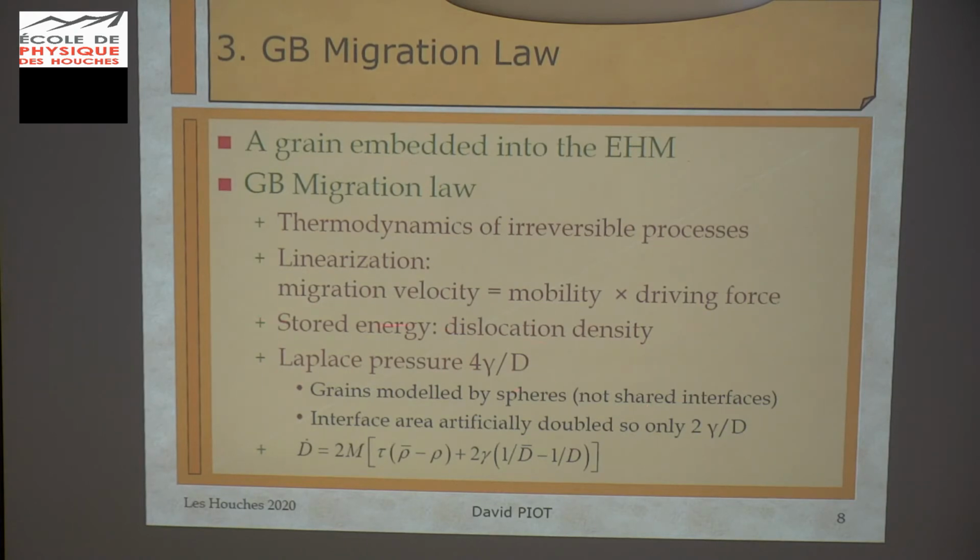There is also another driving force which is due to Laplace pressure or tension, surface tension, or the energy of grain boundaries. In fact, it is the same. But as grains are modeled by spheres in this kind of model, the interfaces are not shared interfaces like a standard grain boundary in a real polycrystal.